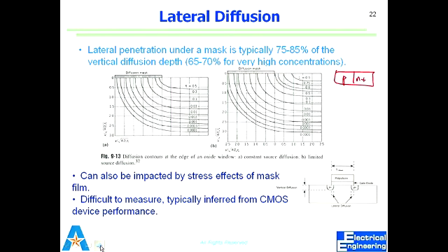In ion implantation, ultimately once you get dopants to their profile, they are treated the same way after that. In case of diffusion, you have pre-dep, which gives you that delta function on the substrate, and after that we do drive-in. In implantation also, we put that delta function, instead of right on the surface, at a certain depth. And then we do drive-in. So essentially after that it's the same.